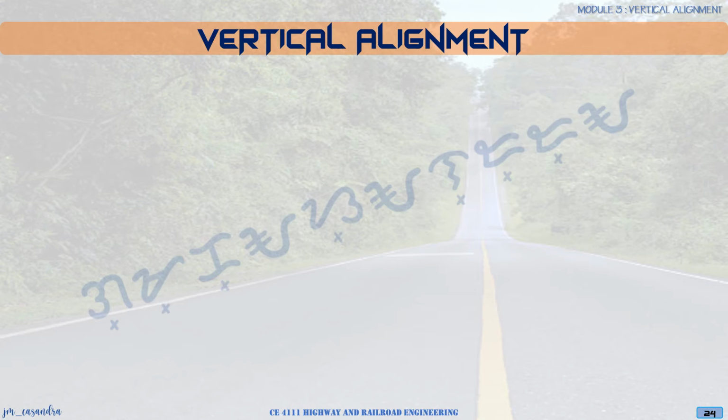So in that case, if you're going to use smaller values of H2, values smaller than 0.6, this would cause a substantial increase in our construction cost. So since we want to have an economical design, we have to follow H2 equal to 0.6 meters.